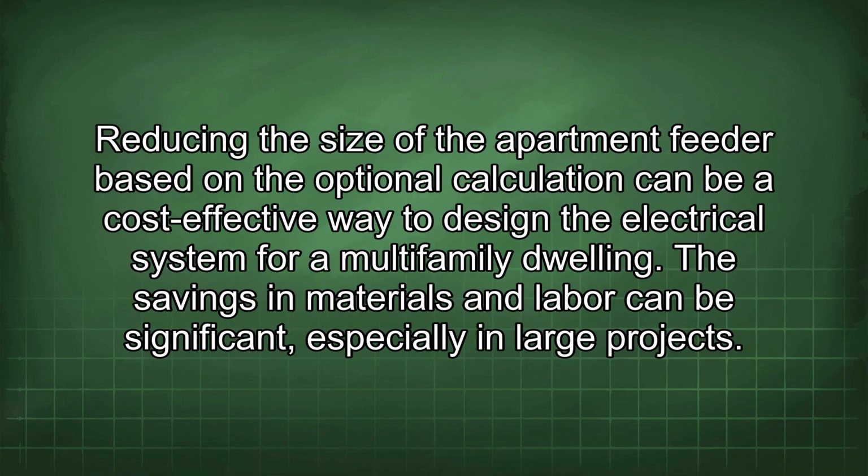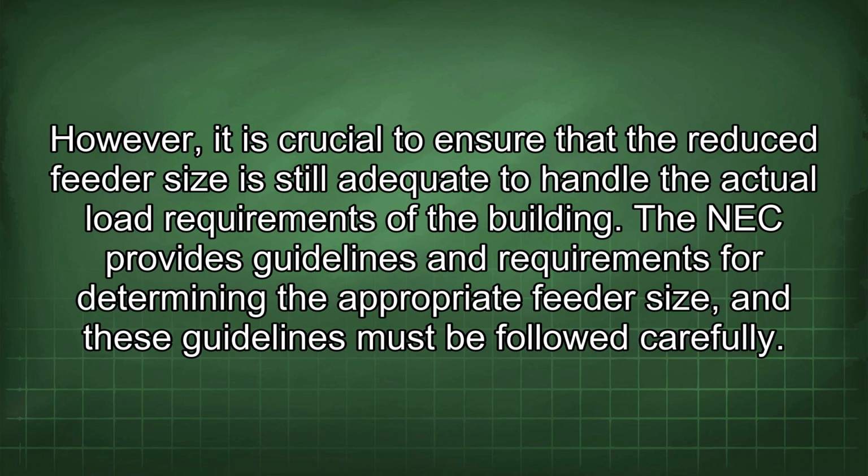Reducing the size of the apartment feeder based on the optional calculation can be a cost-effective way to design the electrical system for a multifamily dwelling. The savings in materials and labor can be significant, especially in large projects. However, it is crucial to ensure that the reduced feeder size is still adequate to handle the actual load requirements of the building.